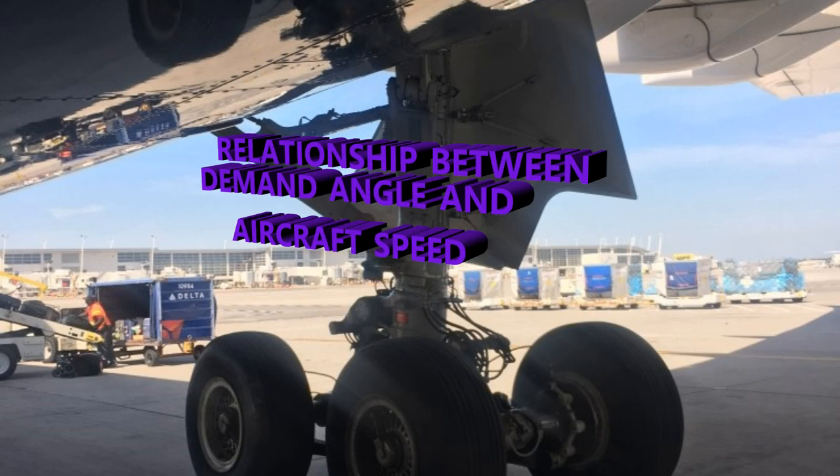Your hand wheel steering orders are only possible if the aircraft is confirmed on the ground, so it gets data from your LGERS system, the landing gear extension retraction system. Your rudder pedals position and the autopilot commands also have a decreased angle deflection authority in relation to aircraft speed, so that's going to be at different degrees.